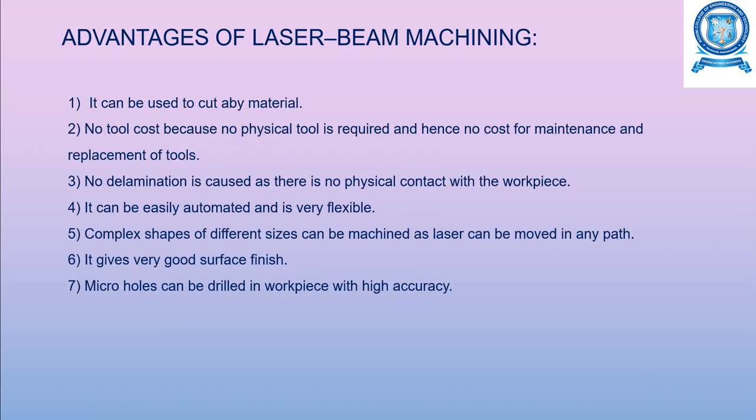The advantages of laser beam machining: it can be used to cut any material, and there is no tool cost because no physical tool is required, and no cost for maintenance and replacement of tools. No delamination is caused since there is no physical contact with the workpiece, and it is easily automated and flexible. Complex shapes of different sizes can be machined as the laser can be moved in any path. A good surface finish is obtained, and you can drill micro holes in the workpiece with high accuracy.